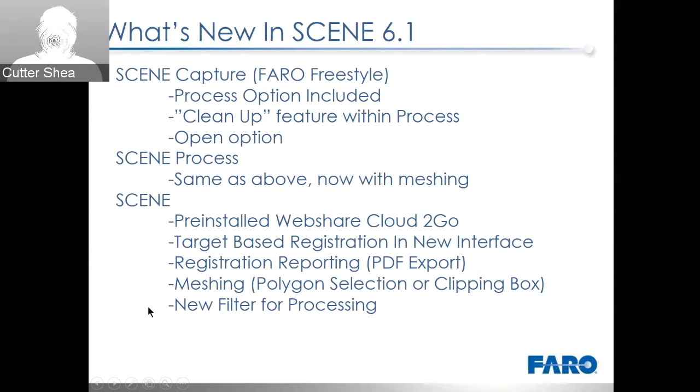Meshing, as mentioned earlier, is another great feature that's been added to Scene. You can mesh entire scans, or you can mesh just a small piece of a scan through the selection tool or by creating a clipping box.